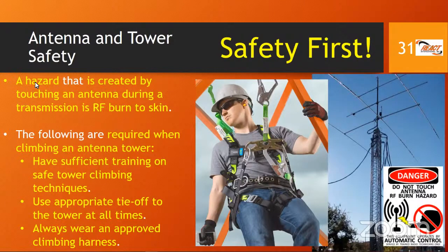So you need to know, and that's an exam question, that a hazard created by touching an antenna during a transmission is RF burn to the skin. And there's a sticker here that tells us that if you touch this antenna while an operator has squeezed the microphone and is talking, they're transmitting, that radio signal is leaving, going through the transmission line to the antenna.